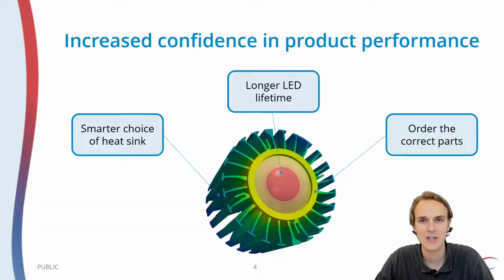And in addition to the operational benefits of doing thermal analysis, you also get increased confidence in your product performance. This allows you to make a smarter choice of heatsink, and you can also enjoy longer LED lifetimes, because you understand that at any given operating condition, your LED is staying within the desired operating temperatures.